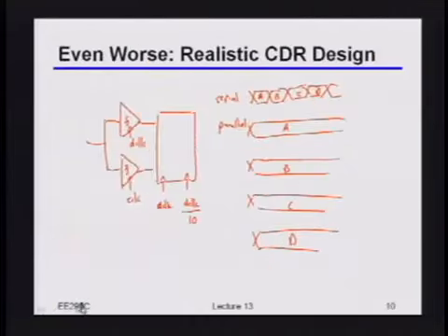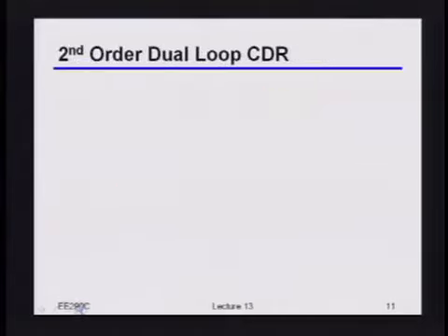So what you've basically said is that rather than just looking for phase, what I should actually do is not build a delay lock loop, but actually build a phase lock loop. Okay? But just to make sure this is clear, we're going to sketch this out because remember that this phase lock loop is still separate from the real phase lock loop we're using to generate the clock in the first place. Okay? So let's just draw what this looks like.